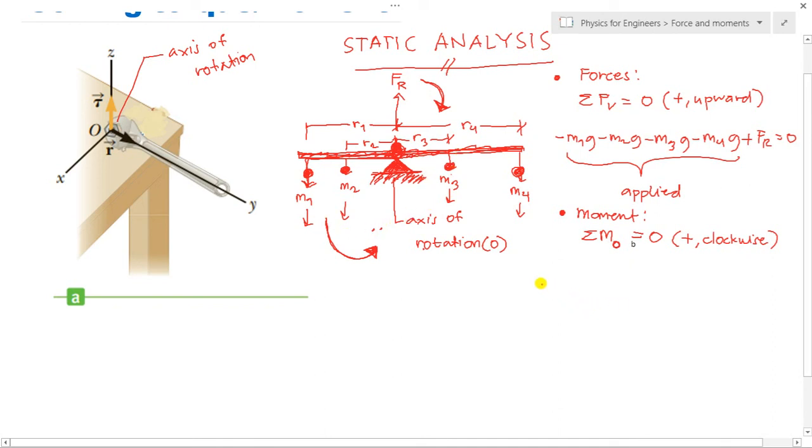So I can just write here the force of mass 3, so that is m3 g. And since moment or torque is force multiplied by distance, that is m3 g r3, plus, since both are clockwise, m4 g r4. Minus next, because m1 and m2 are counterclockwise, so subtraction: minus m1 g r1, then minus m2 g r2, is equal to 0.